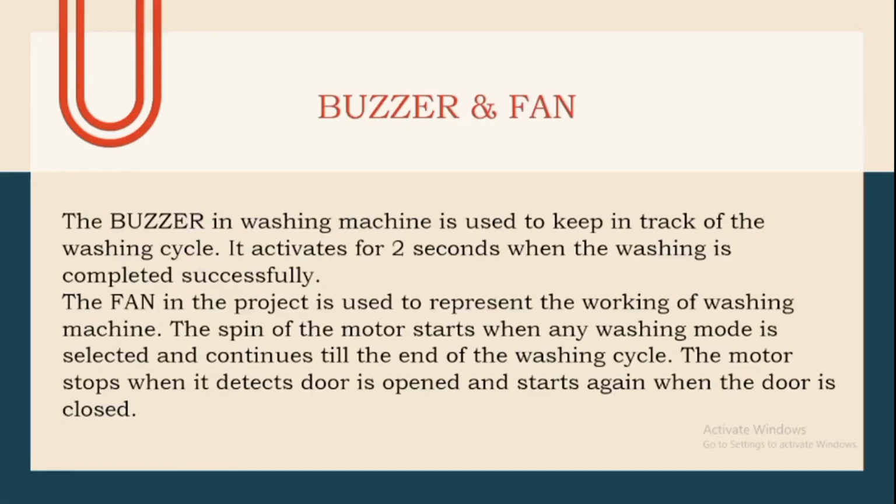And the next slide was buzzer and fan. The buzzer gives audio feedback used to alert the user at the end of the washing cycle. It beeps for 2 seconds after completion. The fan acts as the washing machine's motor. When any mode is selected, the fan spins. If the door is opened, detected by a condition, the fan stops and resumes when the door is closed. This simulates the real-time motor control logic.